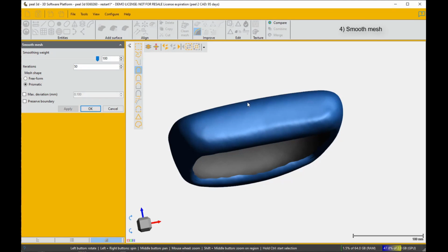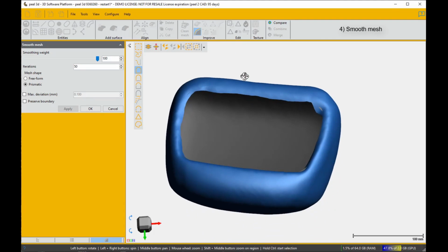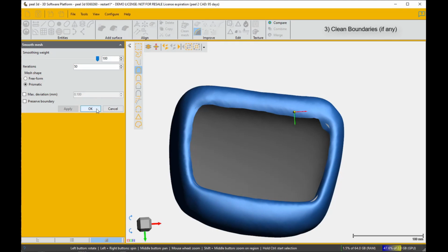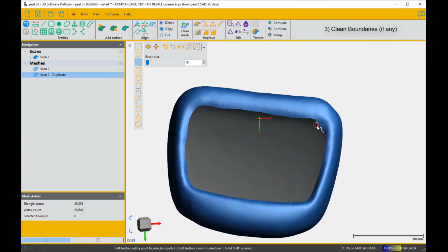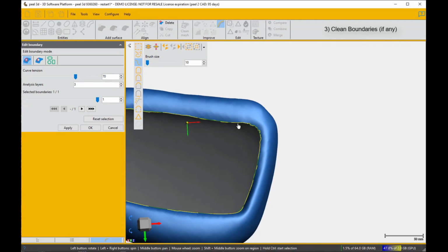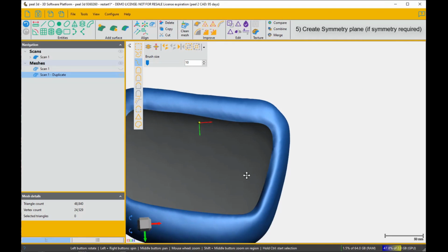And I'm now smoothing. I've just smoothed that mesh because you could before see the seams. And again, ExactFlat doesn't want the seams. It doesn't want a serrated edge. And I'm also just improving this edge top right a little bit as well, because I want to hand over a very smooth set of patches to the ExactFlat software. So I've again smoothed that boundary. That was a little extra.